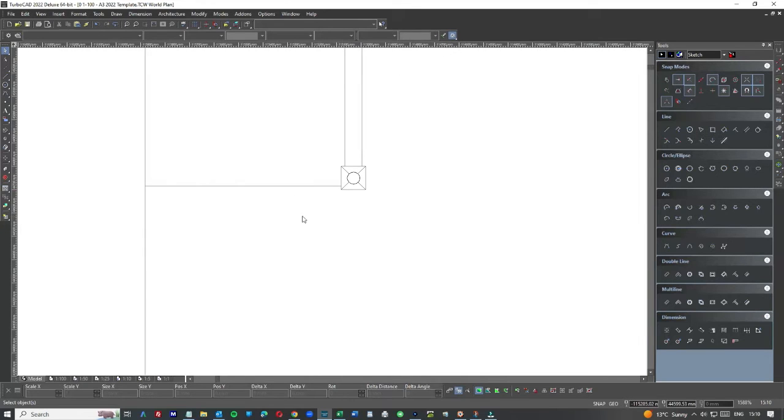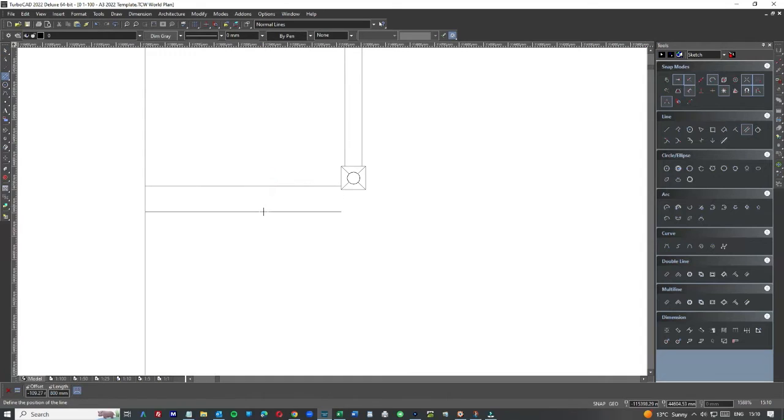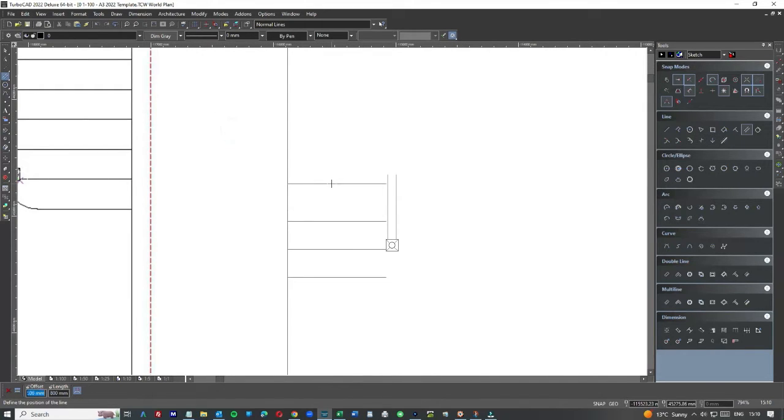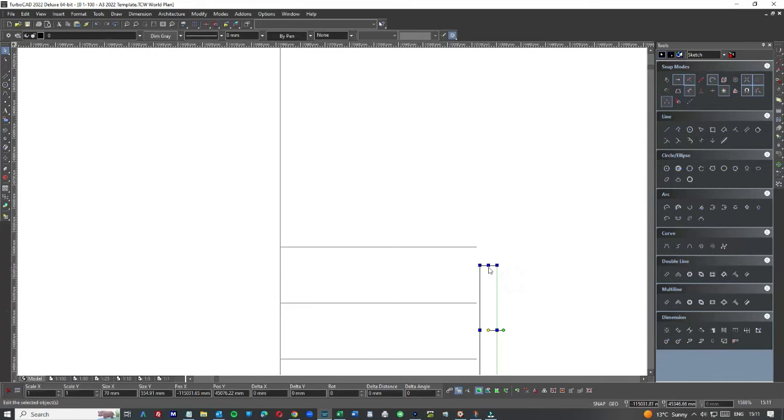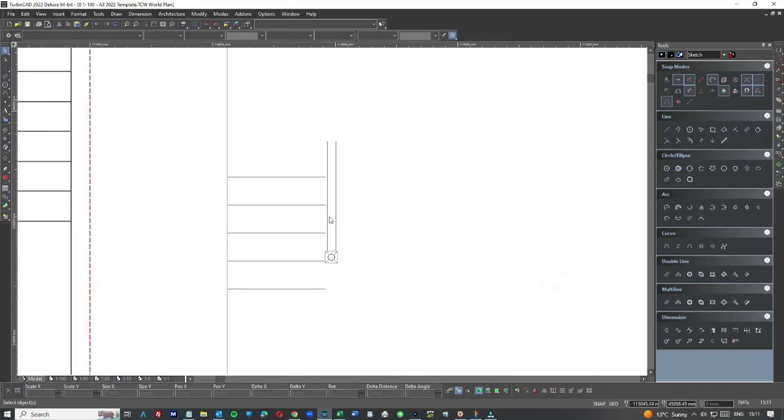Okay, now this is going to be the first tread, so the first tread's got to come out. Let's assume we're doing 240, then tab minus 240, that's your tread. Well, looks big. Let's do a few other treads. Tab 240, tab 240, tab 240. Just pull that up a bit and pull these in.